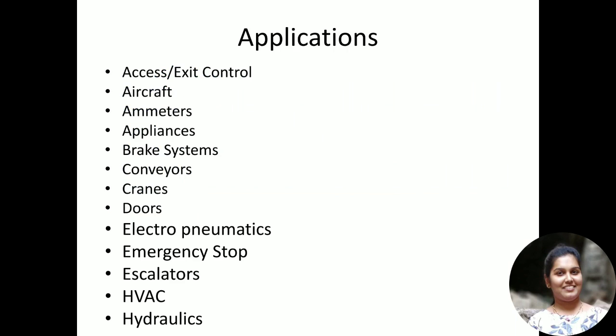So 4 different types have been discussed, and the last one, the rotary switch or intermediate switch, we have not covered in this presentation. But this rotary kind of switch or intermediate switch is a multi-way multi-position switch. It may be costly, but different numbers of throws are available, where many circuits can be connected via a single pole. Okay, so these are the switches that I thought of discussing for today's class.